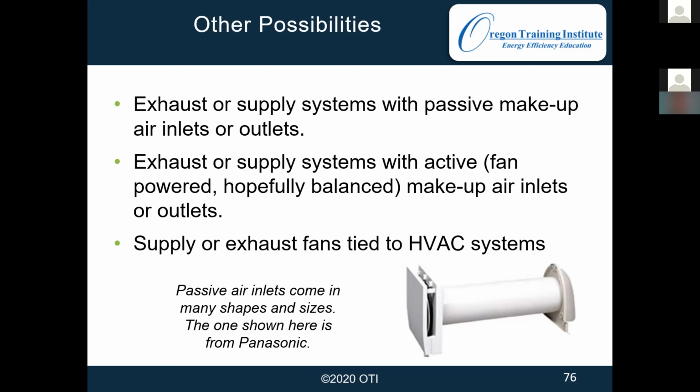Then sometimes we might run into other situations where we need more air coming in, especially when it comes to combustion appliances. And I think on Monday, we're really going to dive into combustion appliances and how they operate and what kind of things make them backdraft. But exhaust fans play a big role in that, and we might need to take that into account before we close out a project. That way we make sure everything works properly and we don't leave the house in an unsafe situation.